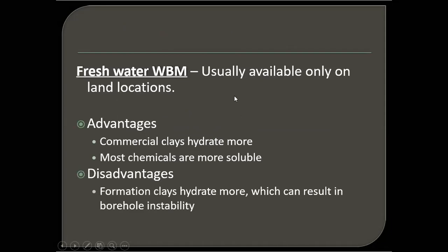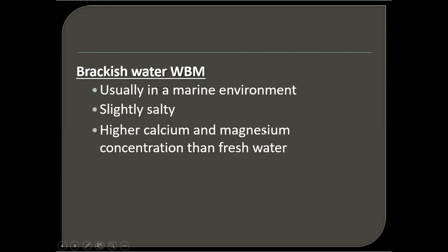Fresh water is usually available at land locations, places where it is easy to drill freshwater formations, and so on. Chemicals are mostly soluble, and clays hydrate more. When the clays hydrate more, they can emit the water and it all goes fine; it does not react with the formation. Sometimes the disadvantage of fresh water may be borehole instability, and for that we have to use special additives to counter this kind of problem.